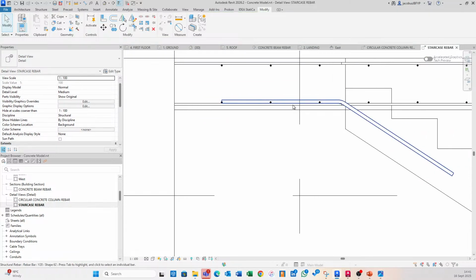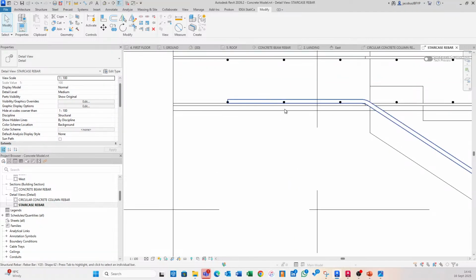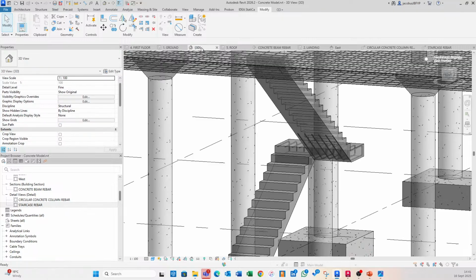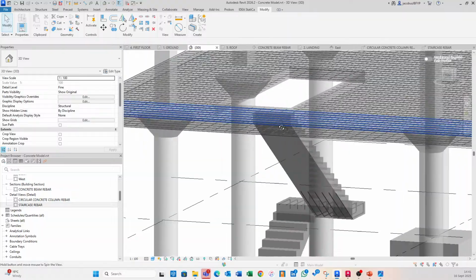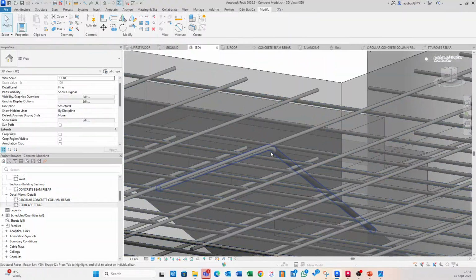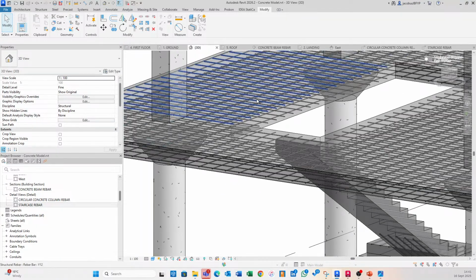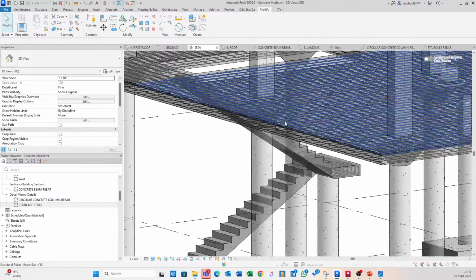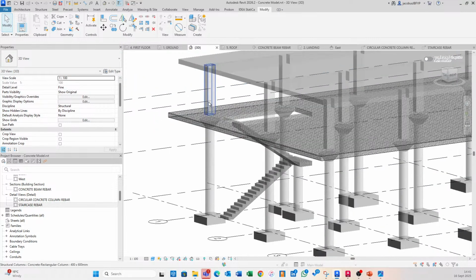So in this case, are you going to fuss over this, or is it something that you can actually potentially live with? Okay, it depends really. It depends, but it's one of those things where if we look at this rebar up here, it actually doesn't look too bad. If we look at it in 3D, doesn't look too bad, but it might be worthwhile to consider whether or not this area reinforcement is really something that you want to go for, or whether you want to detail this rebar separately. It really is up to you, but sections will be the way to go. It's something to be mindful of.